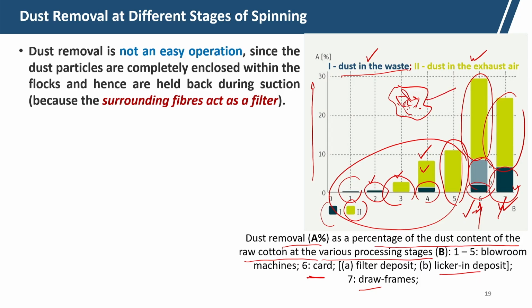So, when suction takes place, the dust which is entrapped within the tuft cannot be removed from these fibers, and it actually acts as a filter. So, your suction is taking place, but the dust is remaining. So, the fiber tuft acts as a filter.